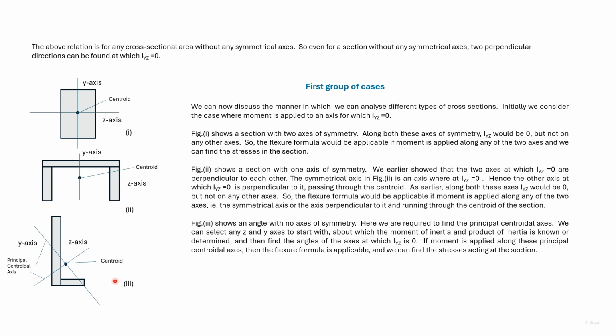That is the principal centroidal axis. Here we have shown the principal centroidal axis. Now consider the load or moment applied along any of these principal centroidal axes or both of these principal centroidal axes. Then using the flexure formula as before, we can find out the stresses at any point of the section.